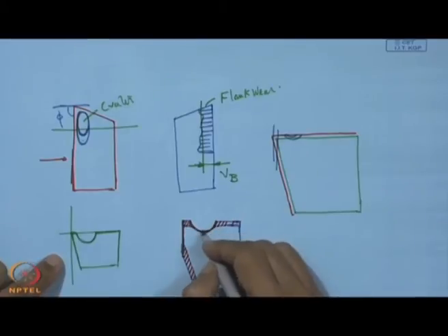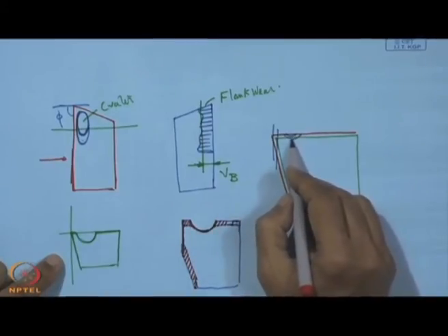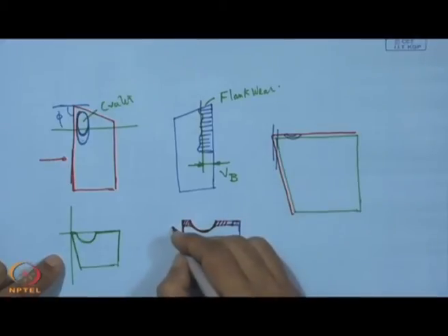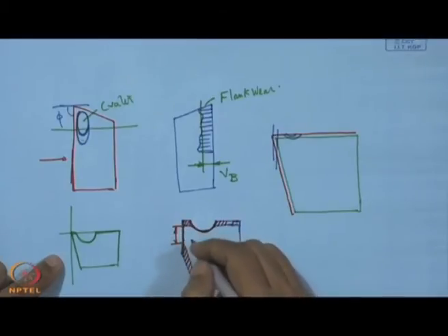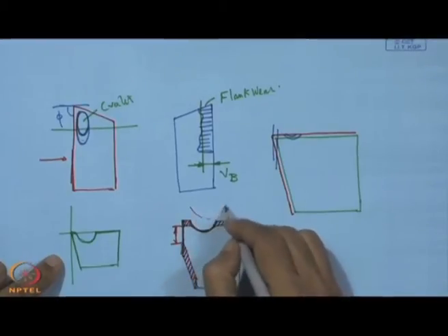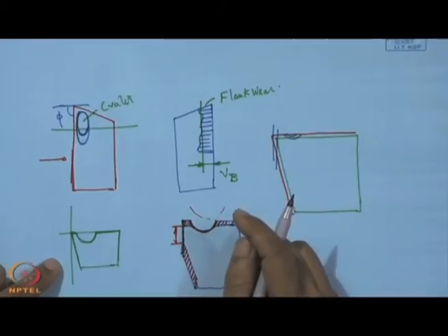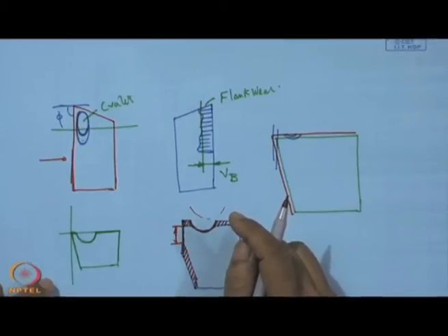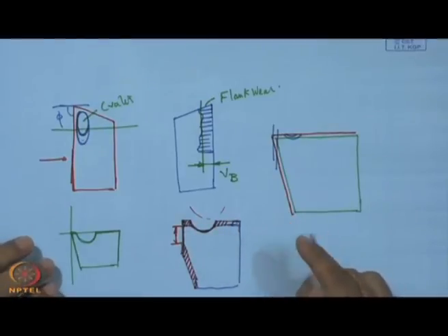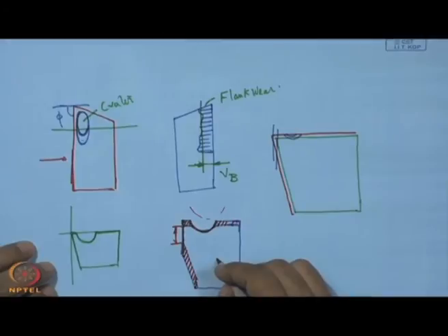So, with this wear pad, though coating is removed from the center of the cavity, or from this zone of the flank, since we have two edges which will support this tool, in direct contact with the machined surface, and here in contact with the chip, these two wear pads on the flank and on the rake surface will still control the growth of the crater. So, the wear rate of this particular tool will be less compared to that uncoated tool.